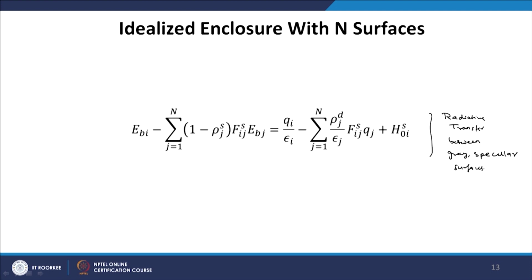Okay. So, this is the expression for partially specular surfaces. This energy balance we will apply to solve a problem. Now, this problem we have solved in the case of gray surfaces also. When we solve this problem, the vertical plate that was used as a reflector to increase the efficiency of this collector plate was not a mirror, it was basically a diffusely reflecting surface.